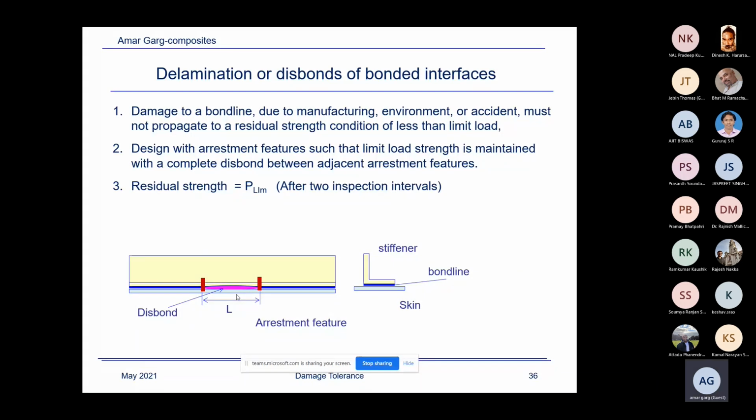So there are still issues about the reliability of the prediction of the delamination propagation by using da/dN as a function of strain energy release rate. I had sent the paper, I think last week or so, and a reference to Professor Dinesh. You asked me about some reference on the delamination propagation. I don't have the electronic copy of that reference, but it is in ASTM STP 917.